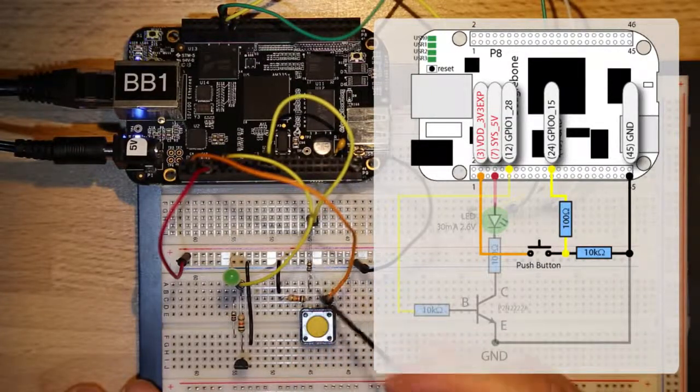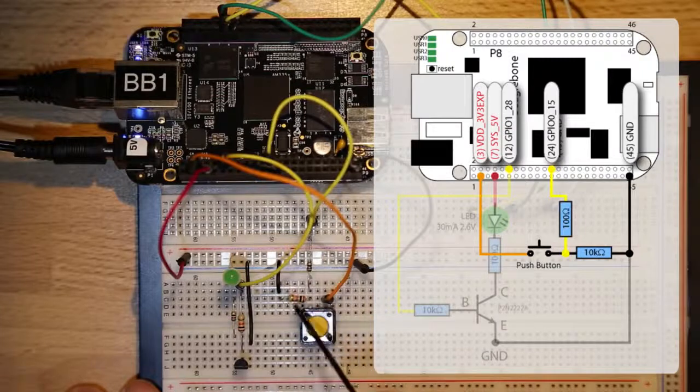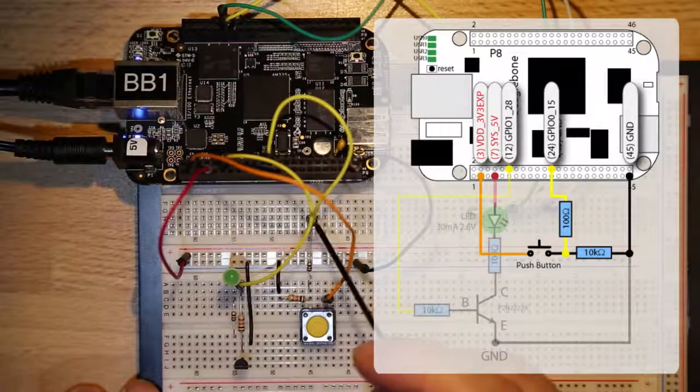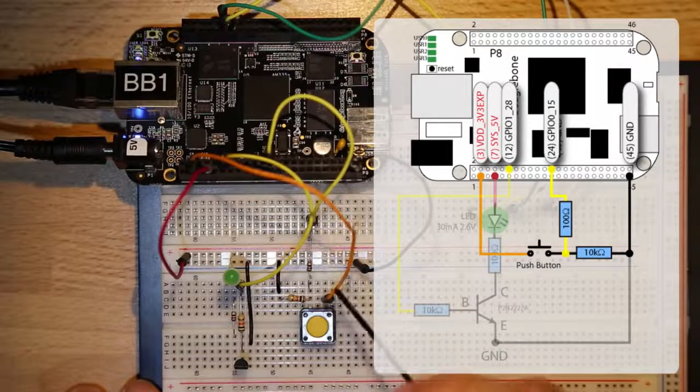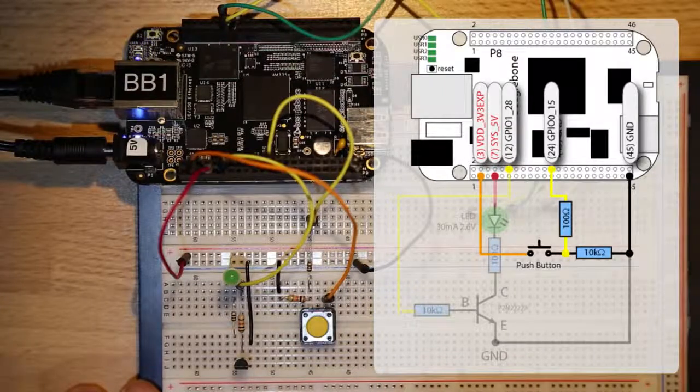So effectively, when the switch is open, as it is now, it's a normally open push button switch, you can see that this line is grounded through these two resistors to ground. However, when I press the button, this is going to short across these 2 points, which means that my point here is connected to my 3.3 volt line via the 100 ohm resistor. So that's my circuit there for the button.